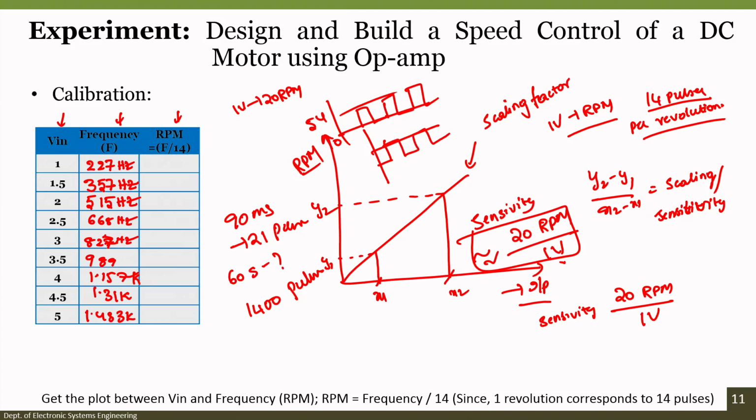If you see the connections of the motor, which we have already seen, the encoder has VCC, ground, as well as C1 and C2. What we have done is connect VCC to 5 volts and ground to ground, but instead of connecting C1 to the CRO, we made this part ground and connected this other part to the CRO.